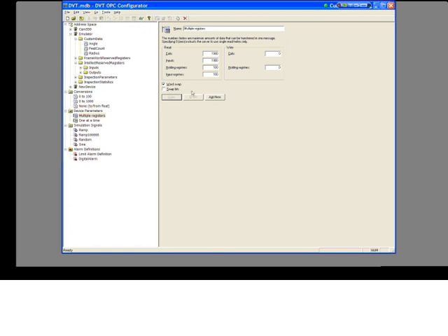Again, in our case, it's not as important to distinguish between them, except if you're maybe writing a bit field data type. In other words, some sort of integer where each bit represents a different value. You can do that as well by using coils. But in general, you're going to transfer some either integer or floating point value or string. In that case, you will always use holding registers.